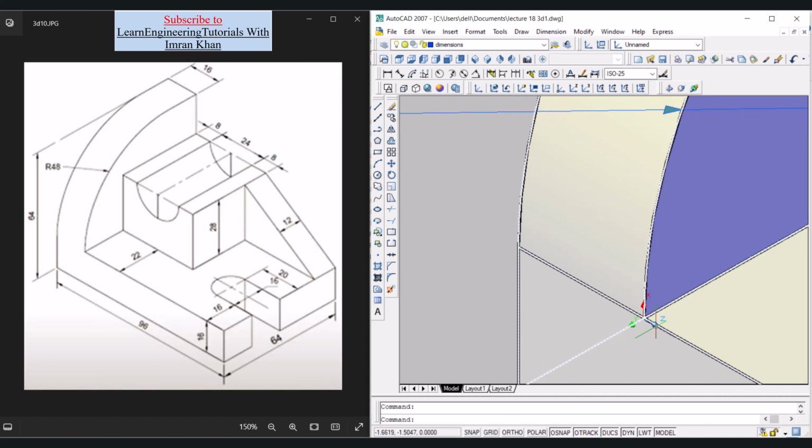How can we fix that? We can rotate this UCS around the z-axis by an angle of -90. So here we will click on UCS. Here we can select this z-axis. So Z, enter. Let the angle be -90.